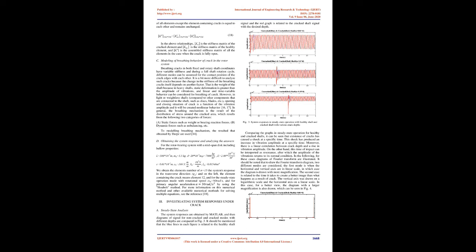Assuming isotropic bearings, the bearing damping coefficients are equal to C_UV = C_VU = 0 and C_UU = C_VV = C_B, where C_B is referred to as the bearing damping value.